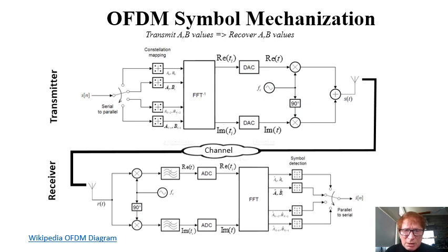The digital analog converter creates a continuous version of the discrete time history that is provided by the IFFT. So far, everything is done on sine waves that begin at DC and extend to the bandwidth extreme, for example, at 20 megahertz with the sine waves being equally spaced in frequency.